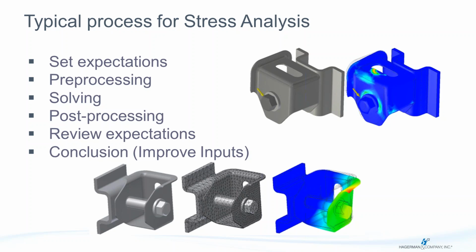To modify those, we can reduce geometry that's complex. We can remove questionable geometry, tight corners, radii, whatever. We can change loads and constraints, change the analysis type, and so on. The refinement is a highly iterative process.